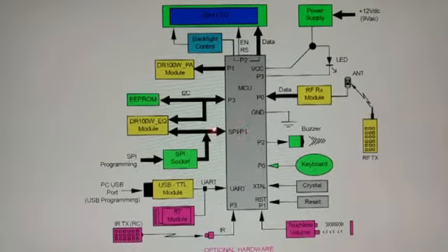The real SPI control is on the programming of the MCU. When we are using the Atmel 8051 core MCU and we want to burn our hex code into the ROM of the MCU, we are going to make use of SPI communications. What we are going to do is have an SPI socket where we put the USB bridge,